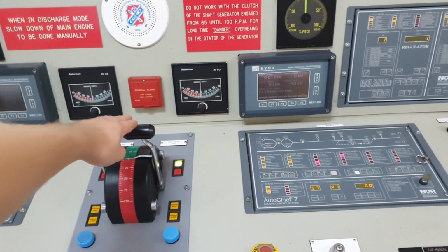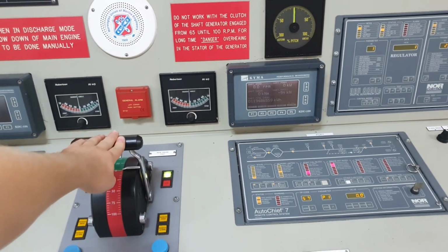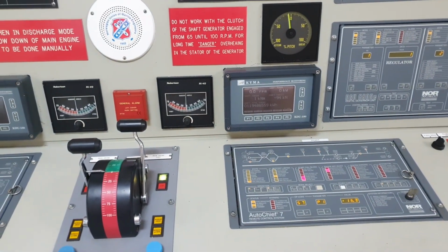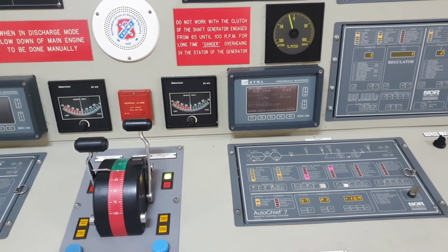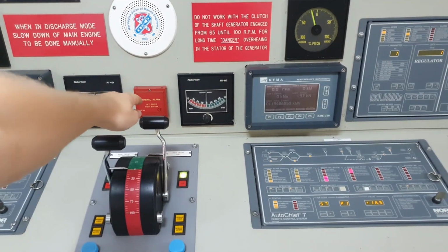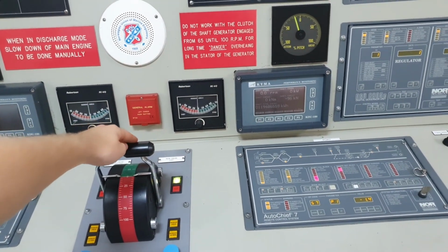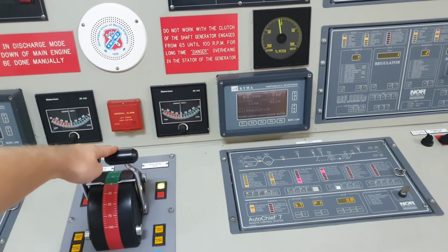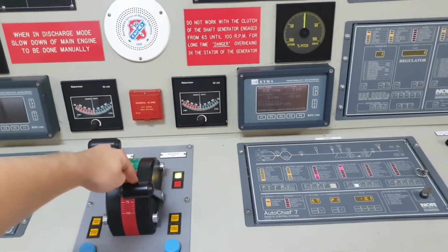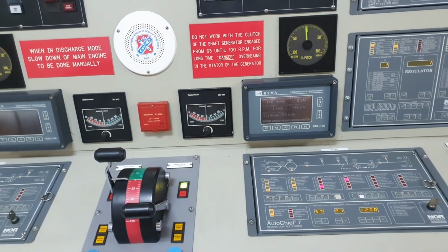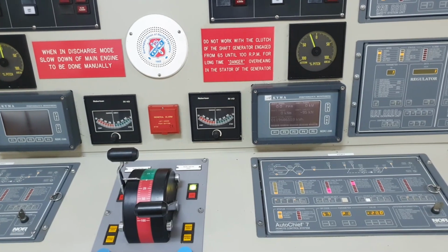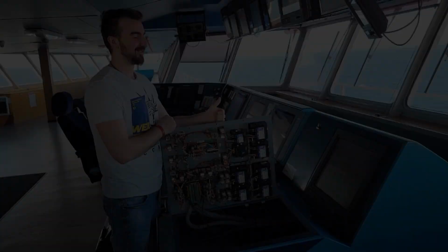After a couple of lever manipulations, the system started working, but the next day in the process of testing the problem returned. Set the lever to ahead and see the arrow goes to astern. Set the astern position and the arrow goes to astern 2. The problem is obvious, the 4-wire potentiometer is out of order.